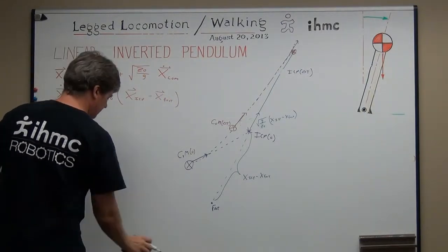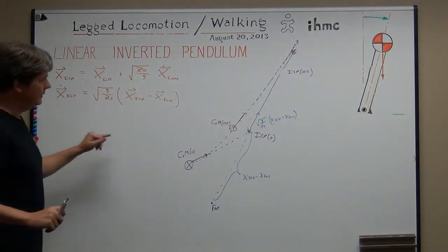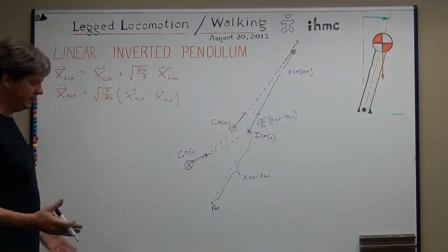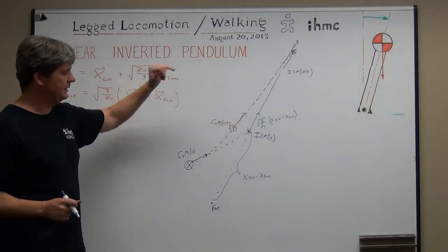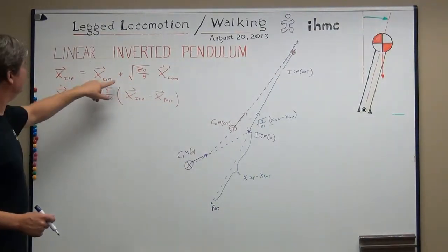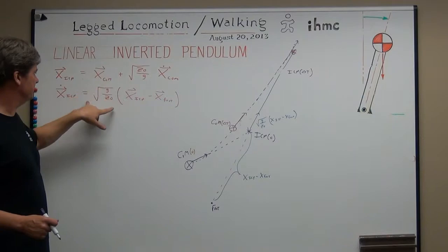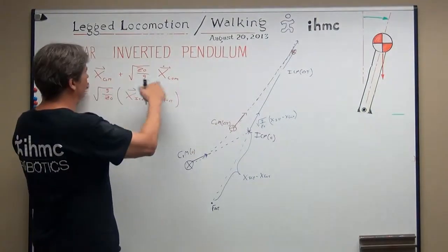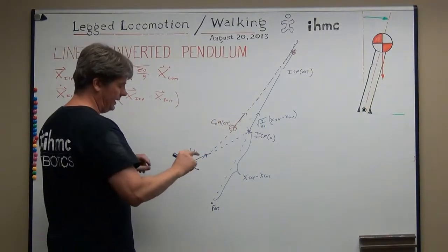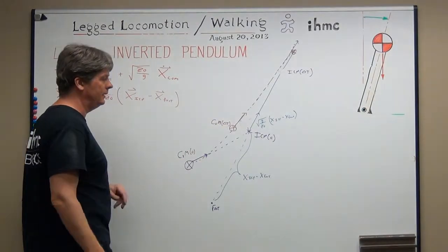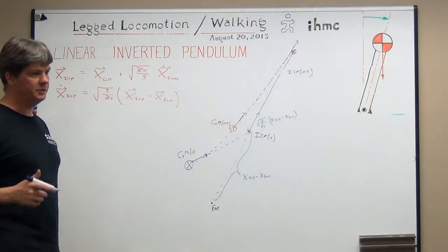So there should be easy draftsman's ways to just draw this by hand once you graph it out. That's the whole point, and what's really nice is this stuff is super fast to compute, and it's easy to look at overhead views to see what's going on. Even though our system isn't a point mass at a constant height, this quantity is going to oscillate around it, so it's a reference. It still obeys this rule for the most part. If you look at the instantaneous capture point for whatever model, and watch what it does with respect to the center of pressure, it pretty much moves away from the center of pressure along a straight line at approximately this rate, even once you start adding arms and all this complication to your model.